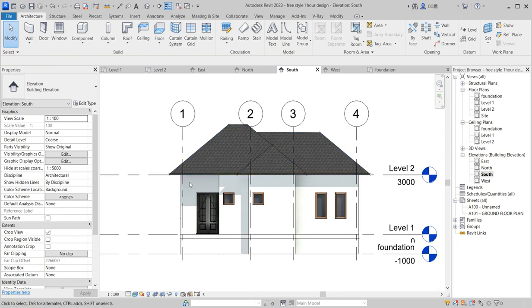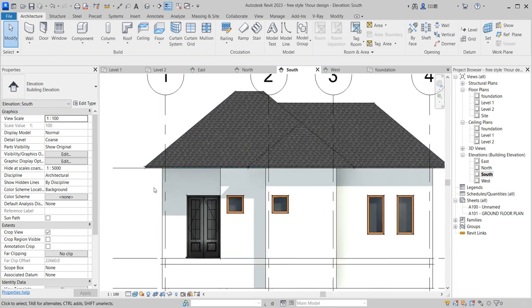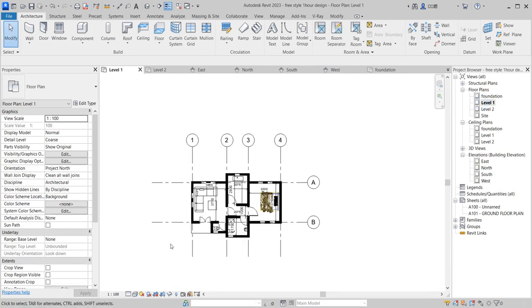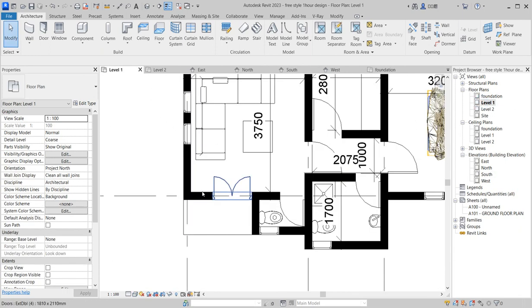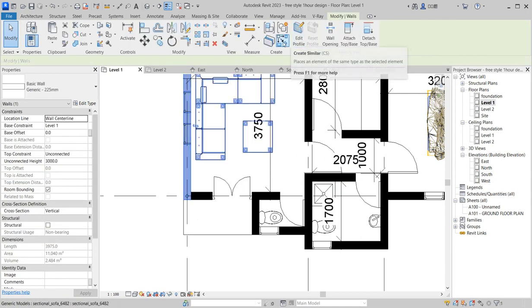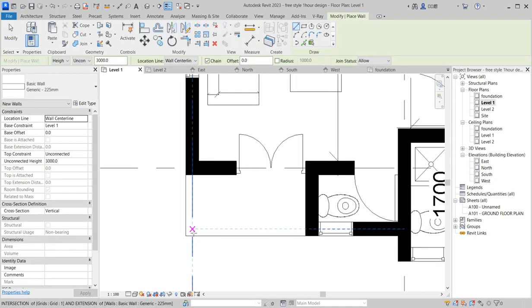So this is the roof that I've created, but this is not the end of what I want to create as the roof. I'm going to change this later, but let me finish with what I want to face. The next thing I want to do is create the roof fascia. Before I create the roof fascia, I have something to do at this archway, so I need to create that as well. This archway, I'm going to use normal block wall to do that. So click here, then select this and then put it here.